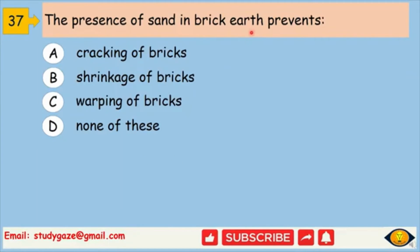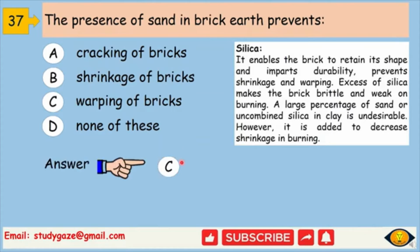37. The presence of sand in brick earth prevents cracking of bricks, shrinkage of bricks, warping of bricks, and none of these. The answer is C. Warping of bricks. Sand contains silica. It enables the brick to retain its shape and imparts durability, prevents shrinkage and warping. Excess of silica makes the brick brittle and weak on burning. Large percentage of sand or uncombined silica in clay is undesirable. However, it is added to decrease shrinkage in burning.